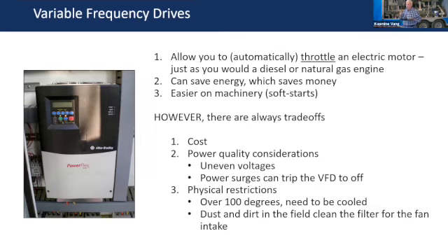The VFD can correct some uneven voltages if they're not real bad. But if they're real uneven, let's say you have 480 three-phase power, and on one leg you've got 540, on one leg you've got 410, and the other leg you've got 460, that's uneven voltages. The VFD might be able to straighten that out a little bit, but that might be too much and it might trip the VFD. And fixing that will help keep your motor and other equipment better for longer, because you can talk to your power company, your power supplier, and say, hey, we need to get this voltage issue taken care of.